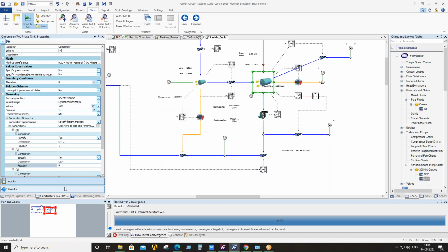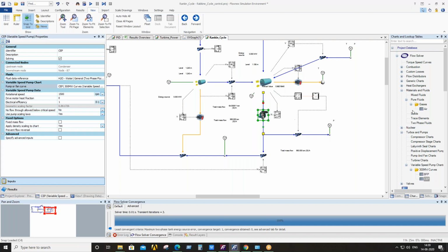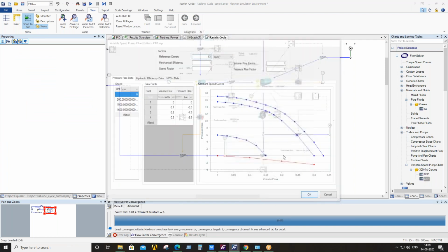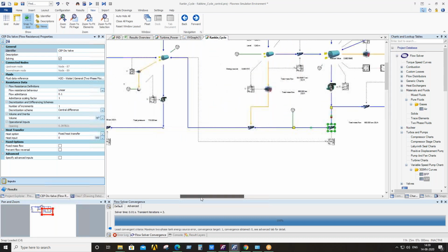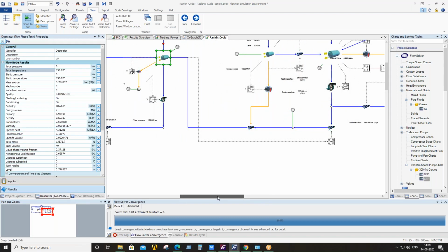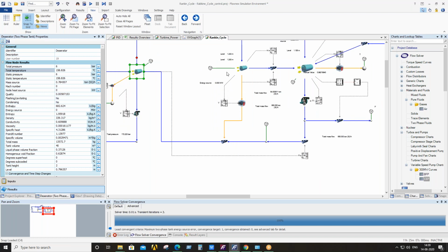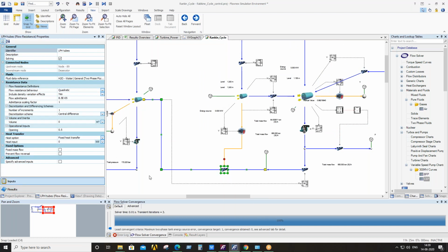Suppose here you can see the fluid density in the condenser reaches around 63.77 kg per meter cube. According to that, whichever curve you assign, you can specify the fluid density here, so that the pump will operate for that density of fluid. After the CP, this is the condensate regulating valve, which is utilized to regulate the deaerator level. The CP develops some pressure, and this is our condensate line, and here it is one simple model for the LP heaters. It exchanges heat with the LP heaters, and from the LP heaters it goes to the deaerator.